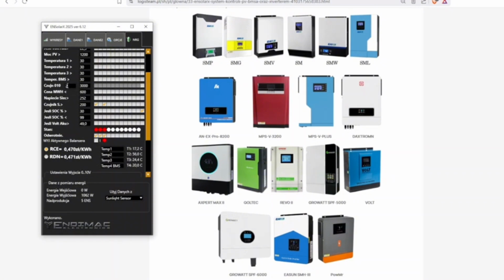If I marked it, it would work exactly the same way as it does now, but if I had, for example, from 2 to 2000 here, it would only work in the range from the minimum to the maximum. So if it exceeded the maximum, it would also turn off the output from 0 to 10 volts. And if it's marked even after exceeding those 2000, it won't turn off this output as if to 0. So it's generally better, it's probably better to have it turned off. It depends where, in what situation, who needs it.